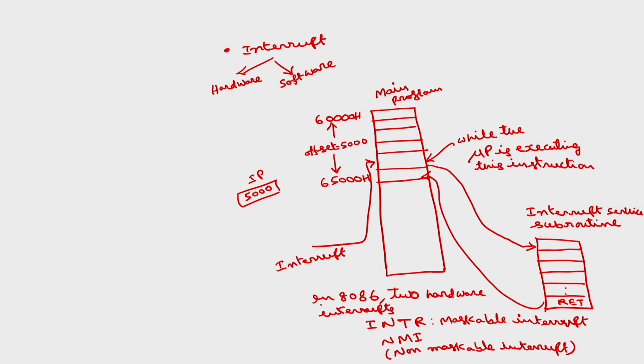But when will INTR be enabled, and NMI be enabled? INTR is called a positive level triggered interrupt. INTR is positive level triggered.